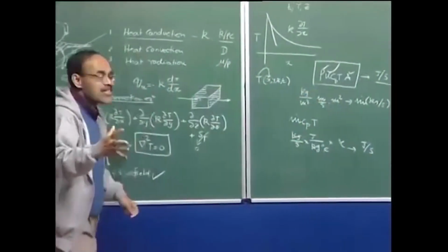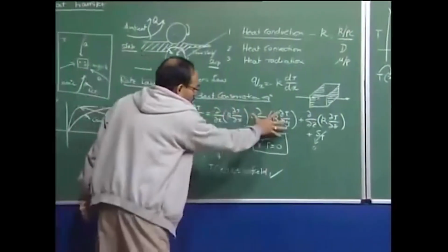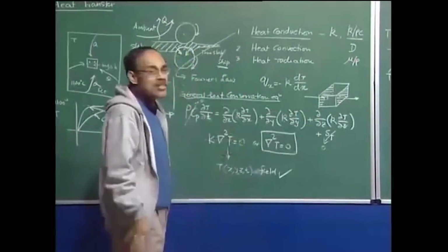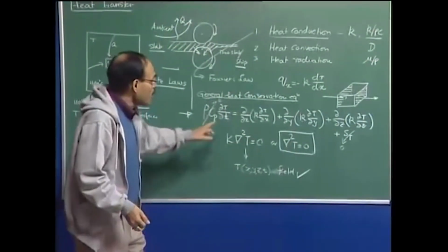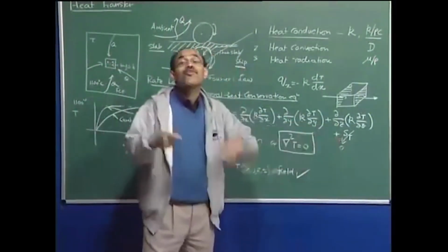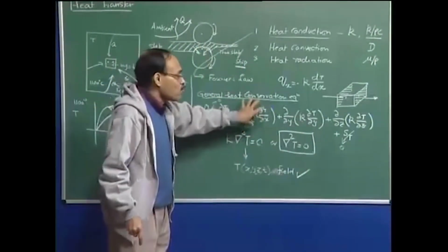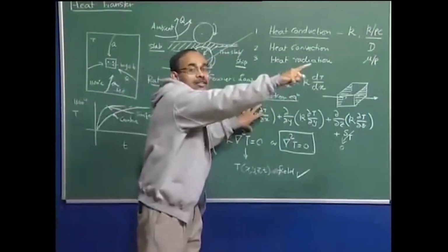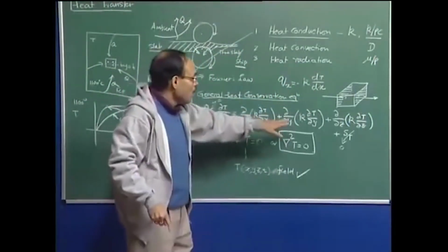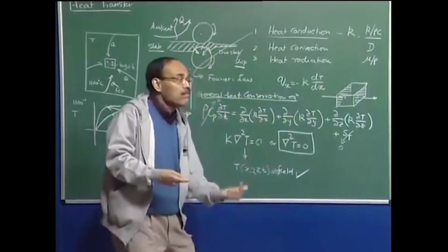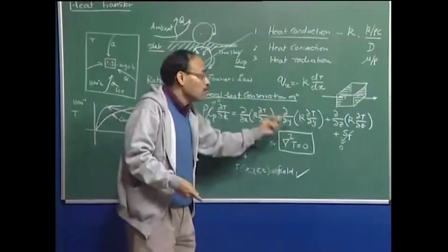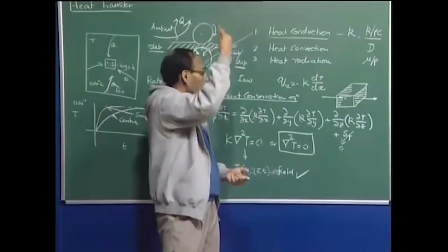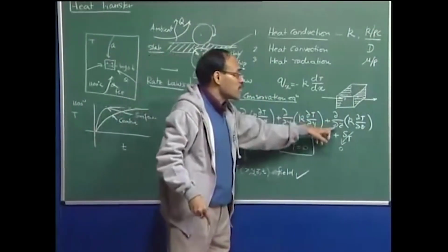So, we can understand that if I have to write an energy balance equation for a fluid element where heat is flowing because of both conduction and convection, I will not have 4 terms on the right hand side, but I am going to have 7 terms. In the x direction, 1 conduction term, and on top of that, heat will be flowing by convection also. In the y direction, heat flows, for example, here only due to conduction, but now I am talking of a fluid element. So, in addition to that, I am going to have convection, and so it is in the z direction.